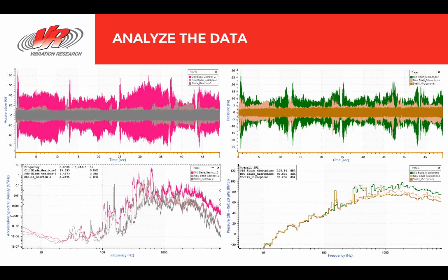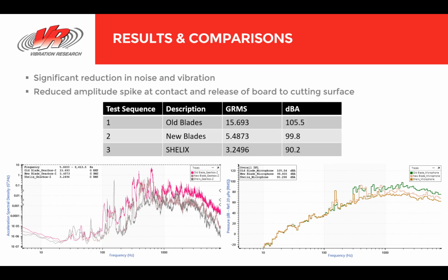So once there are boards in contact with knives, the cutting motion is not perfectly perpendicular, which reduces some of the noise. And also the fact that there are constantly blades, the same pressure is on that wood throughout the entire pass, significantly reduces the amount of noise and chatter that is generated by that cutting motion. So here's just a review. We can see the differences.